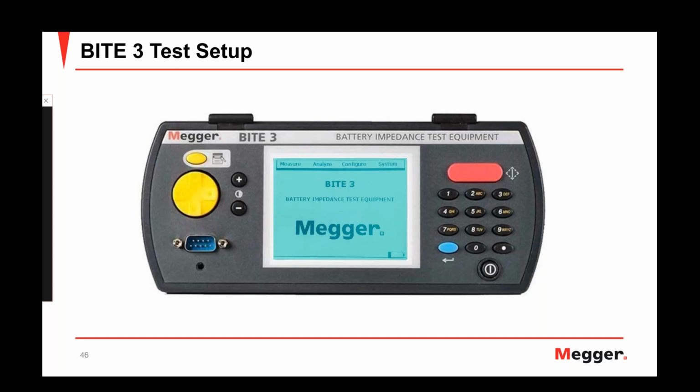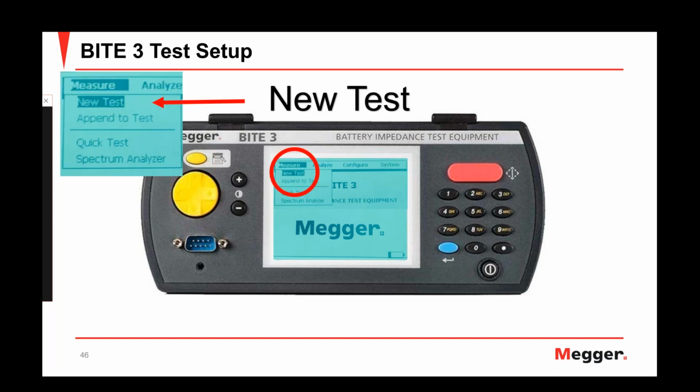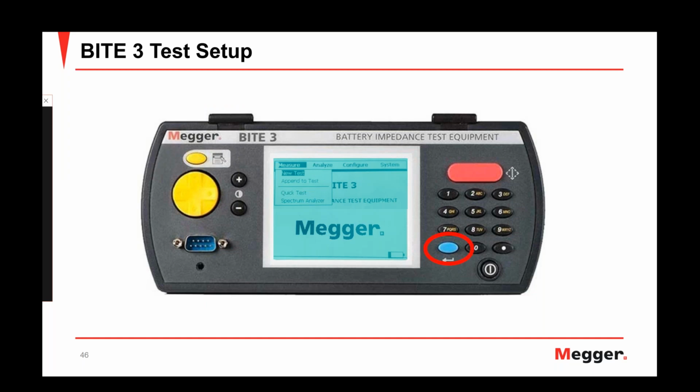So let's now talk about how we're going to set up the BITE 3 to begin the test. To do that, you're going to press the black power on button so that we can boot up the instrument. And after we've booted up the instrument, then we're going to go ahead and press the yellow menu button to bring up the menu for a new test. So go ahead and highlight the new test function and then click the blue enter button to proceed with the setup.